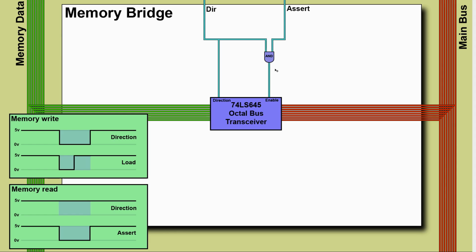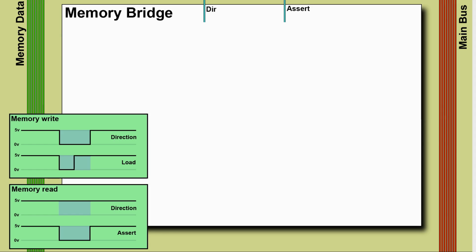And so we can be pretty sure that we're not going to see contention on the main bus, because those lines, there's only ever one that's low at a time. But if we stick this AND gate here, I'm a little bit worried about the time delay on the AND gate. This may be nothing for me to worry about, but I'm kind of paranoid about these things at the moment. So what could happen here is the enable here comes on very slightly late, and then it will stay on very slightly late as well. So it's possible that this will be asserting to the main bus for a tiny fraction of a clock cycle while another device is asserting. So I wanted to look at other ways I could do it where I would be more confident that's not going to happen.